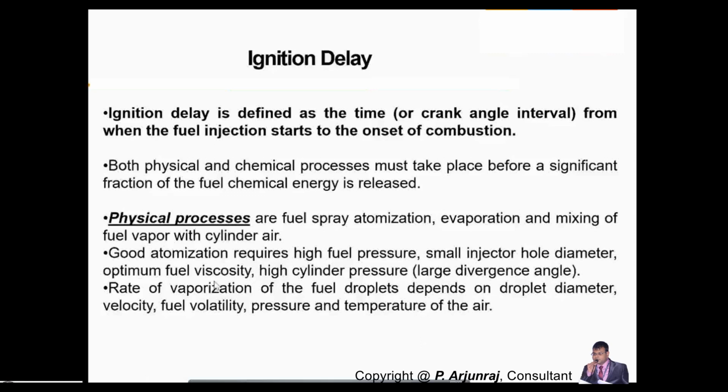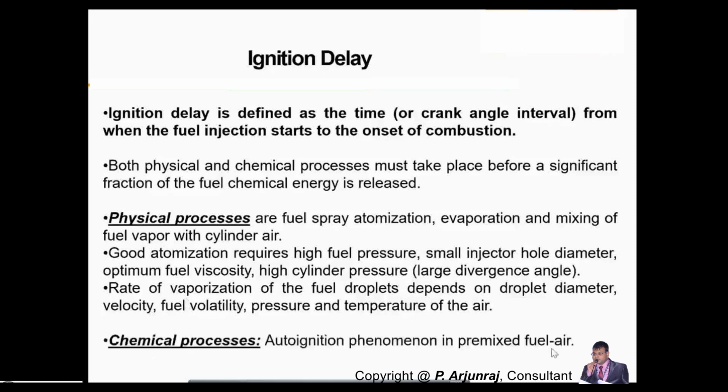If you have high viscosity, the delay will be higher, because the fuel density should be at a certain level. Otherwise, it takes some time for the combustion to take place, which again increases the physical delay. Even the cylinder pressure will contribute to the physical delay. The rate of evaporation of the fuel droplets depends on the droplet diameter, the velocity at which it travels, the fuel nature and volatility, and the pressure and temperature of the air.